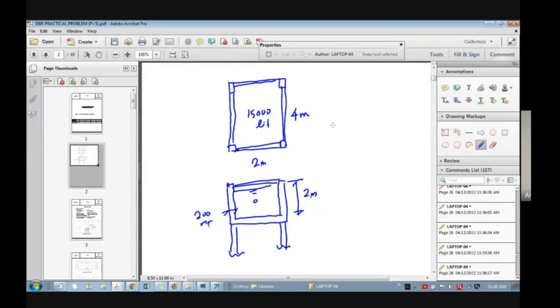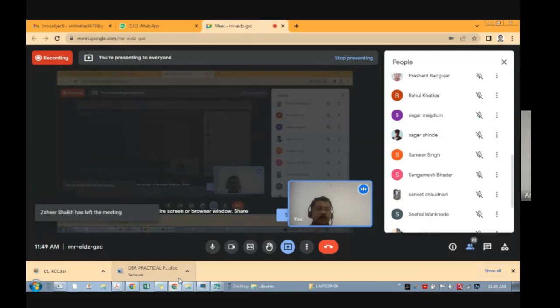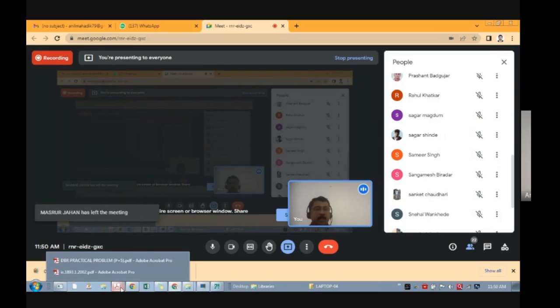Then you know the water inside the tank and the thickness of wall, so you can calculate the weight of tank. There are 2 things. Either you can calculate the total weight of tank and apply the load in the software, or you can model the water tanks also. This way you can mention the overhead tank details in the DBR. It may happen that we require any other information also. You can mention everything here. If there is communication with the architect and they are saying something, add that point also.